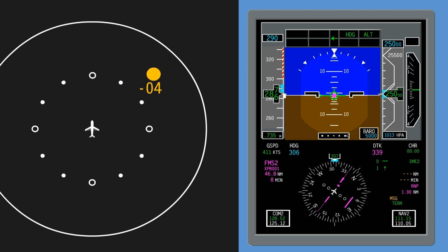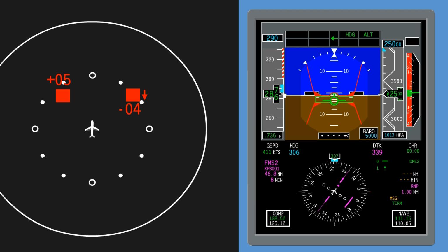Traffic. When the TCAS detects an RA condition where certain ranges of vertical speed are not recommended, preventive RA, one red trapezoidal avoidance zone is displayed. When the TCAS detects an RA condition and a maneuver is recommended to increase the vertical separation, corrective RA, Descend. One or two red trapezoidal avoidance zones and a green rectangular fly-to zone are displayed.